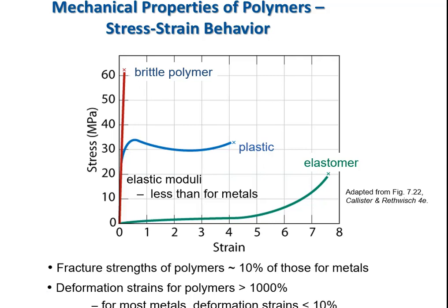So when you're uncoiling, you can get tremendous deformations with very little stress. But as you begin to align those chains such that you're now stretching and pulling them apart rather than simply unkinking them, they'll start to pull back quite a bit harder at those larger strains, and then we see the stress rising. So that's why the slope of the elastomer green curve rises so much more between strain 5 and 7 versus, say, between 2 and 3.